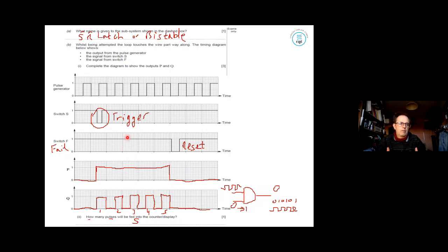Okay, important summary from there. Recognize a not S, not R latch. There's the latch, also called a bistable. You trigger it by using zeros, and you reset it by using zeros. And the other thing, don't have two zeros going into not S, not R latches, because it gives you an indeterminate output. You don't know what you're going to get.